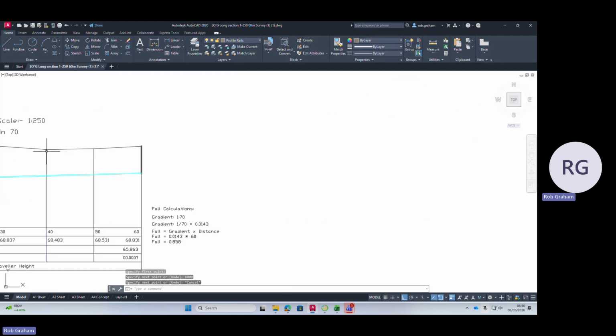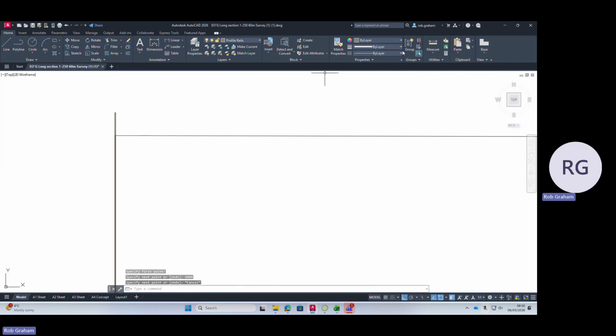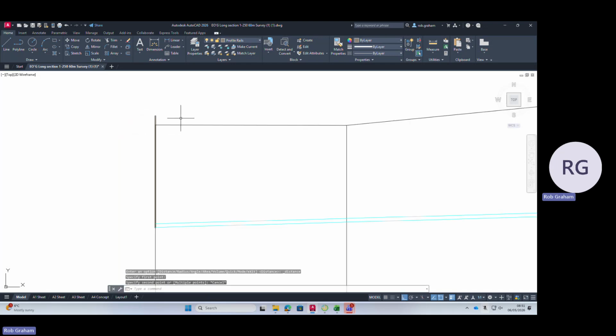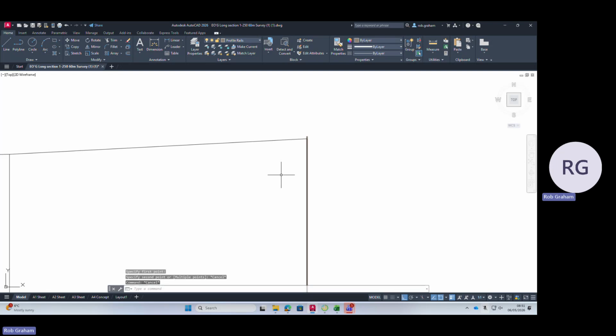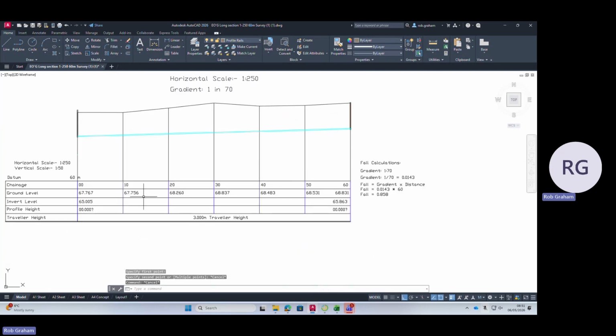And what we want to do then is measure the distance that protrudes from the ground. Our distance here that we're protruding up is 476. So 476 divided by 2, that's only 238 mil on our scale. So that's nearly ground level, so that doesn't meet our 0.5 to 2 meters. And over here, if we check the distance, 64, so it's only 32 mil above ground level. So as I say, it's trial and error, and that one hasn't worked for us.